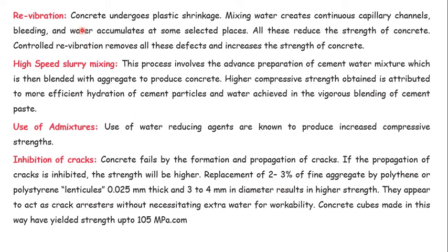Revibration. Concrete undergoes plastic shrinkage. Plastic shrinkage means when fresh concrete is there, there are small cracks, so volume change will be there. That volume change is known as plastic shrinkage. Mixing water creates continuous capillary channels, bleeding, and water accumulates at some selected place. All these reduce the strength of concrete. Controlled revibration removes all these defects and increases the strength of concrete.